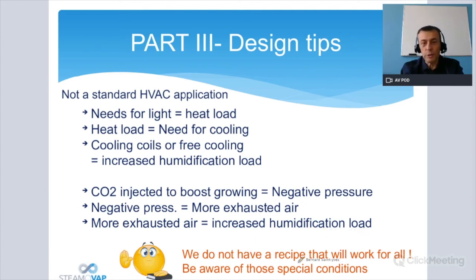As I said, we don't have a recipe that will work for all, but just be aware that it's not a standard HVAC application, and ask these kinds of questions. Is it a dedicated room? Is it indoor? This will tell you what kind of cooling they will use, and the capacity of the cooling will eventually give you the need for humidity to add because of this. Do they have negative pressure, CO2 injection? Questions like these will help you see if they have planned for everything they need.